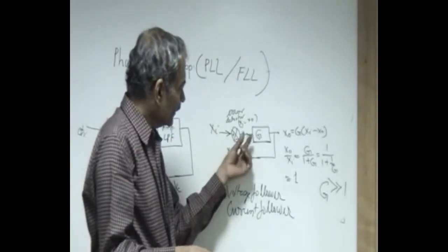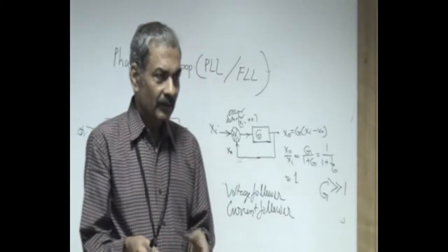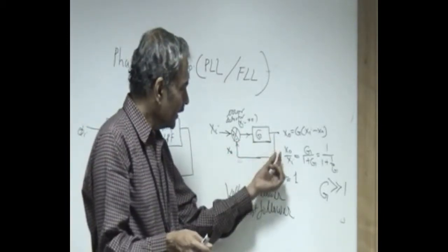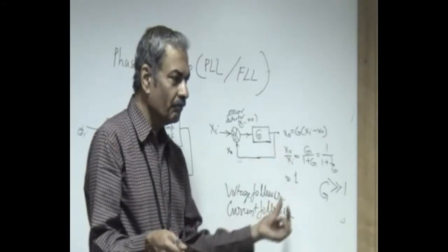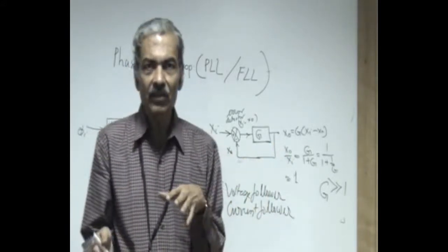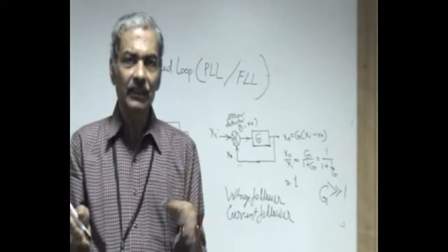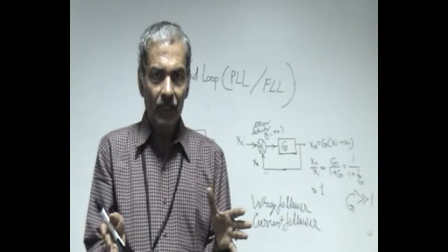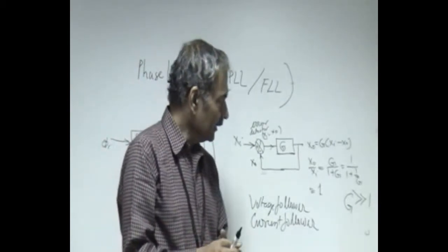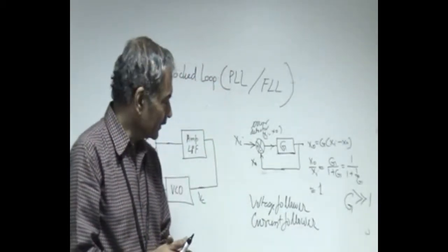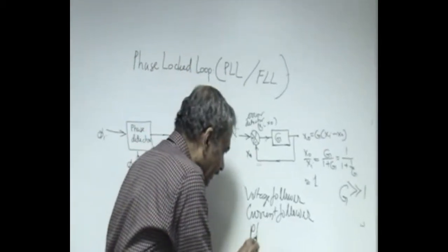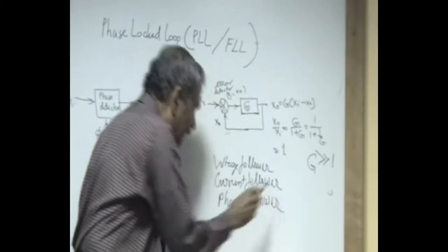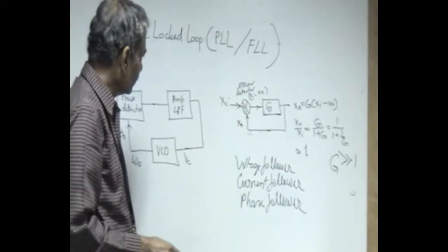Then passing through a low pass filter and an amplifier increases the loop gain, and that voltage is converted back to phase by using what is called a voltage controlled phase generator, which is nothing but a filter that is tuned by a voltage. That we had seen in the earlier experiment. So that is called a phase follower, which is a true phase lock loop.